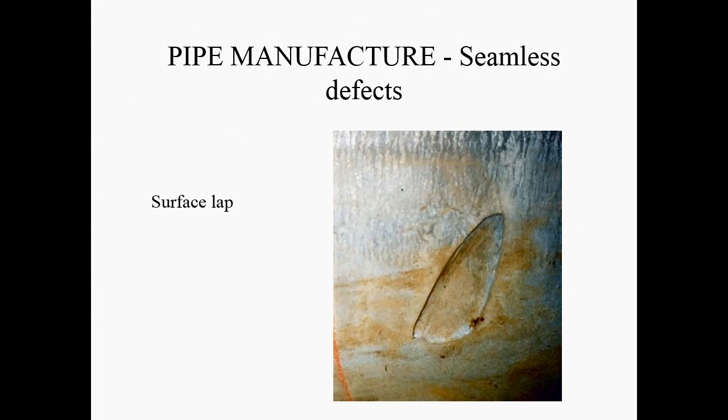That's another surface lap picture. If you wander around the pipe dump in many process companies that make pipe for the industry, there will be all sorts of failed things. So this is a classic surface lap. It started with a surface lap here, and then the cracks run in, and then this has been peeled off effectively. So we get this vertical crack around the edge and then this angled crack at the start. And you can see that's on the outside.